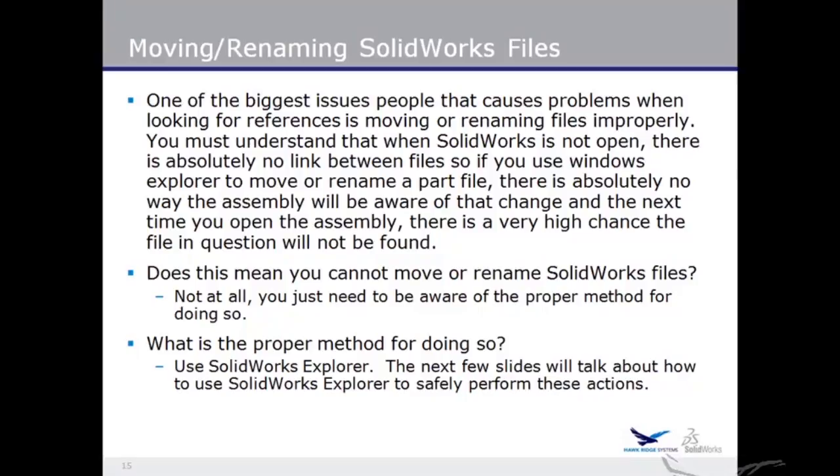Okay, so the problem here is that Windows has absolutely no idea that these SolidWorks files are connected together. When they're open inside SolidWorks, SolidWorks obviously understands that, but as soon as you close SolidWorks and you're just browsing your C drive or browsing the server looking for files, Windows Explorer has no idea that there's references here.